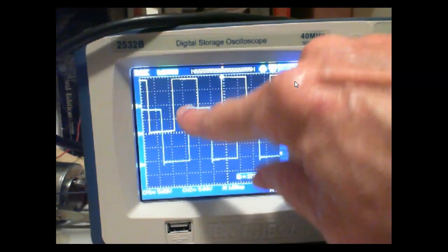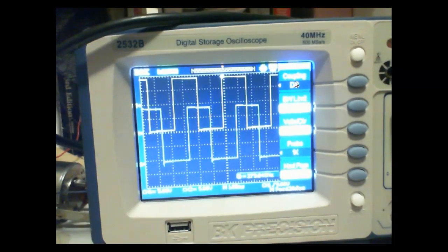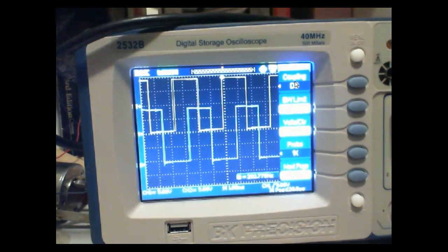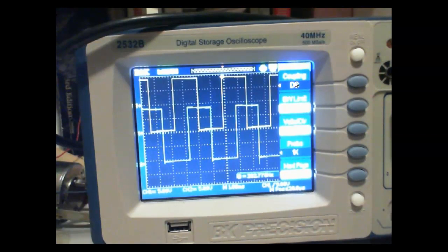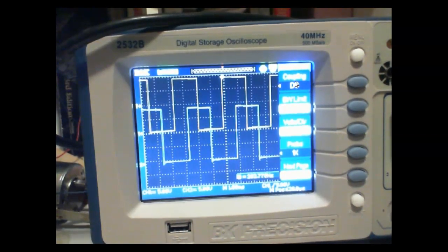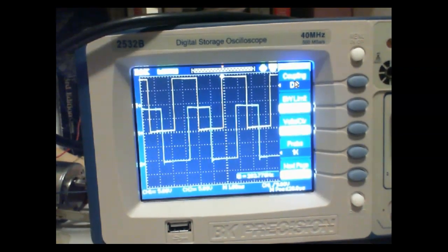Now, yellow leads blue. So I know y'all see the colors, but the bottom one. What we can do, depending on which one occurs first, this would tell us what direction the motor's running.